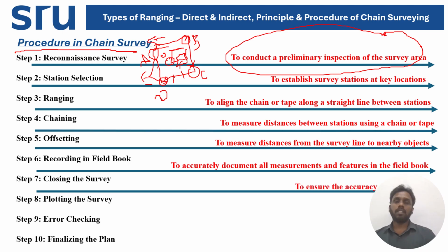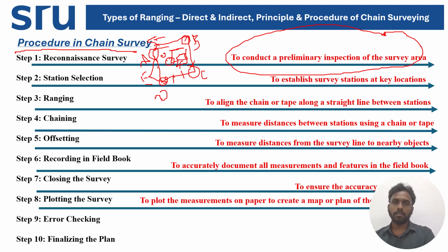Then once everything is completed, to ensure accuracy of your work, you close your survey at the end of the day, or you continue the next day, depending upon how much you are assigned. Okay. So you are closing your survey. Then after that, plotting the survey, right? This is very important. You record the data on a rough sketch, then you convert your data into a proper understandable sketch.